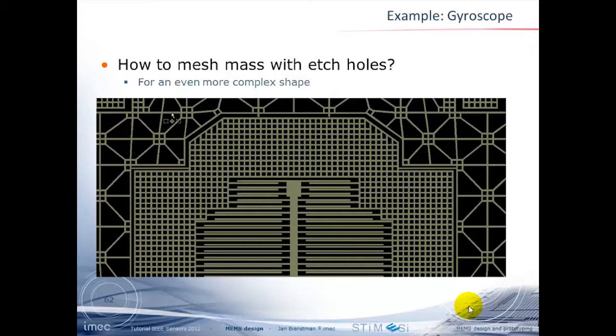You just draw, and you draw the holes. But for a layout, it's already different. So I advise people not to make one very long polygon of it, because your DRC checker will choke on it. Your foundry will say, hey, I don't like it. So preferably, people ask you to draw the area around, and in another layer the holes. So that was the way.